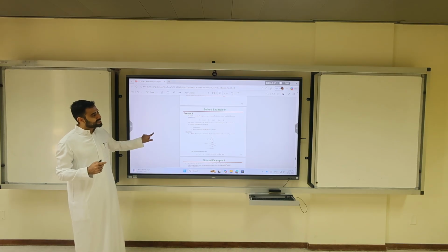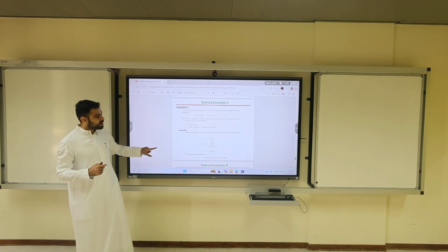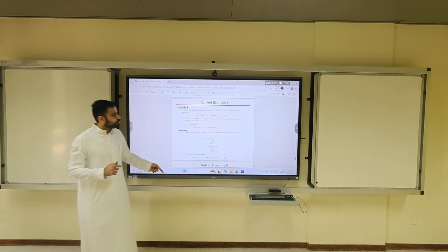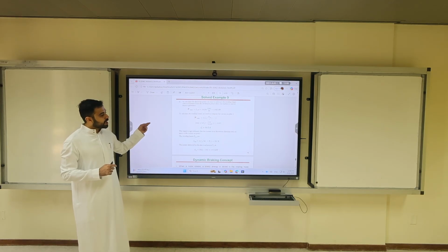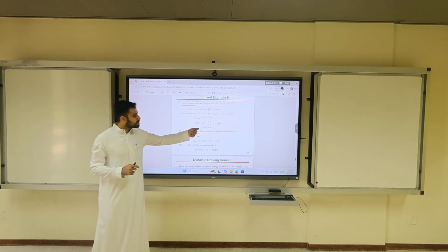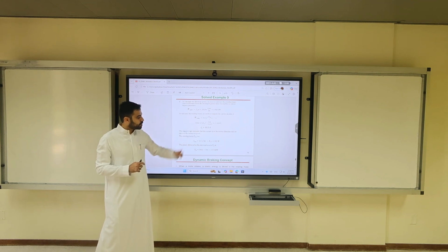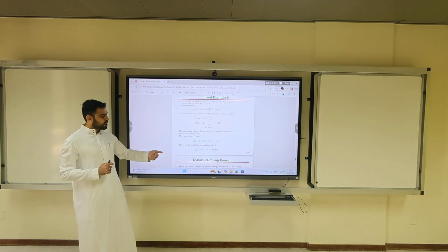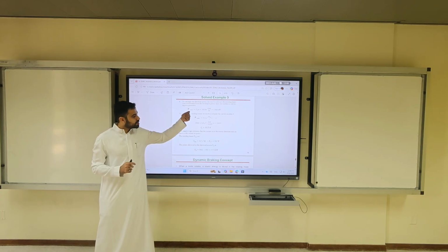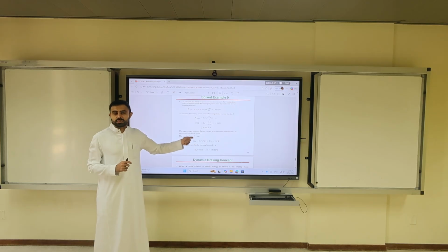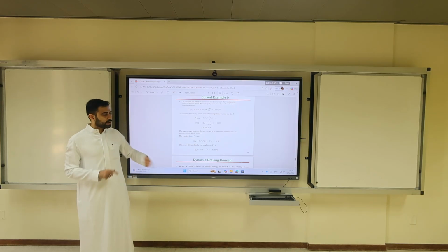Also, we did before example 9, where we had a negative slip for the induction generator. This was for the regenerative braking, and we calculated the current that it generates using the power equation. It was 10.5 amp. Then we calculated the power delivered to the supply, which is the power converted minus the losses, I square times R1 plus R2 prime.